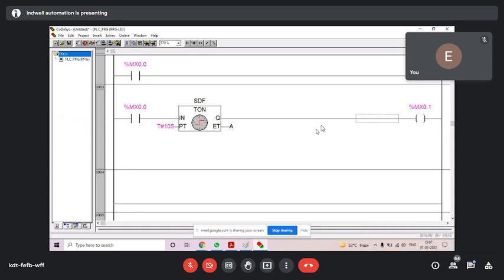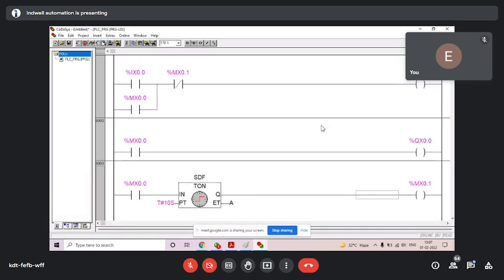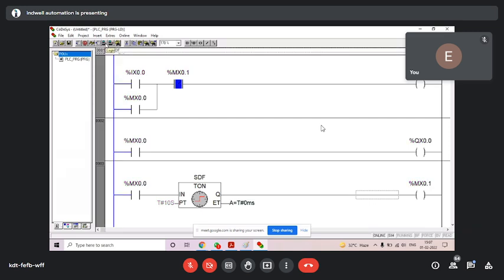Actually, you will have to keep patience because I shall show you visualization also, so that you can make all examples at your home. First, I shall show you the execution in ladder. You have to do login, run. This is important in ladder: I0 should be on, it is a push button, and immediately I0 should be off.